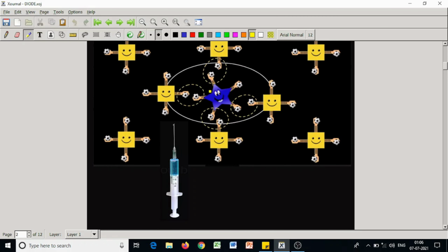In an n-type semiconductor, a pentavalent element, say arsenic, is doped. Silicon is replaced by a pentavalent element, say arsenic. When a pentavalent element like arsenic is doped into silicon, it replaces one of the silicon atoms and shares its 4 electrons with the neighboring 4 silicon atoms, and the 5th electron becomes almost free. The energy required to dislodge this electron is only 0.05 electron volt.